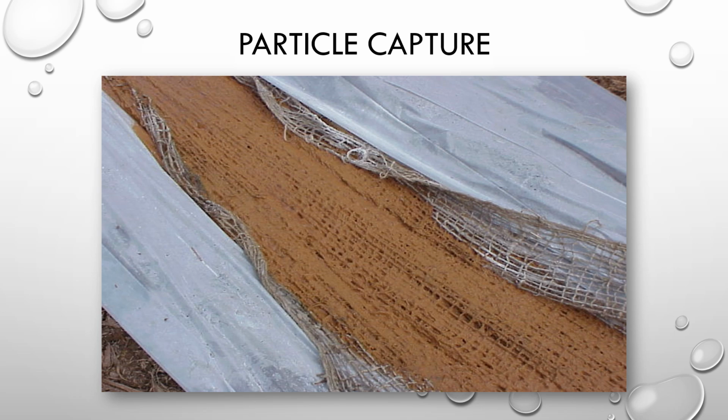For particle capture, a couple of things to note about the jute matting. If you run a project for a significant amount of time or have very high sediment loads, eventually your fibrous mattings are going to become saturated. At that point, you can lay more matting down on top. If you can, now you have a polymer and sediment laden jute matting that's biodegradable. We've had some people take those and use them as erosion control matting on other areas of the site, so they could potentially be reused. Another thing to note is that the polymer is non-hazardous. It has no special disposal considerations, so it could also be hauled away to a landfill.